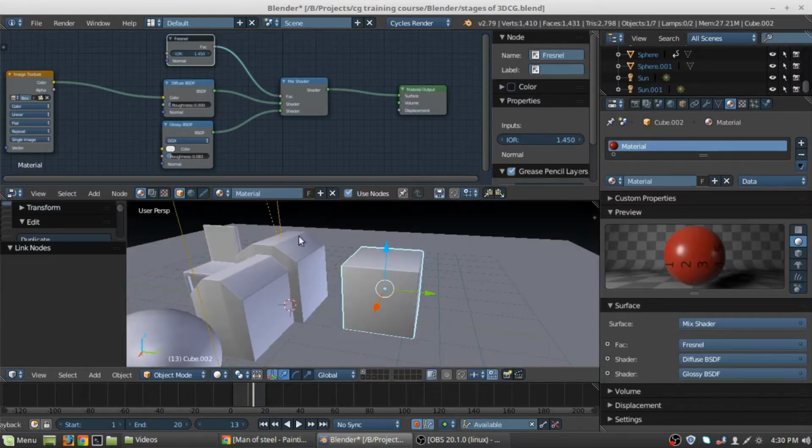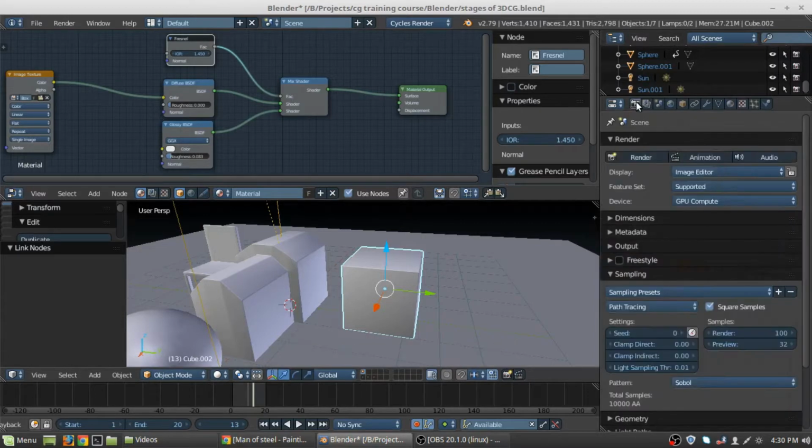So first, let me go into the Material tab, and in the preview, let's just type 10, and for render, let's just type 20, because this is just for explaining how you go through different stages and do different things in Blender and Cycles, rather than a detailed or in-depth tutorial for rendering. So we will keep things simple and just explain how things are done in Blender.